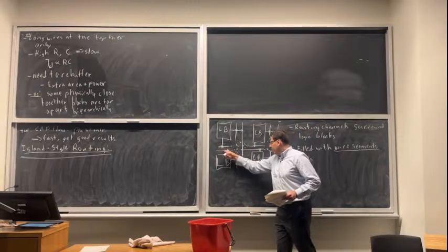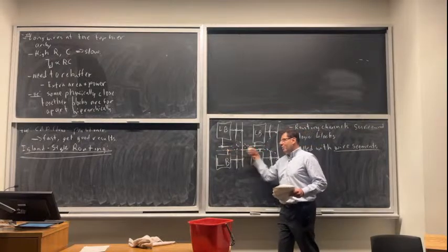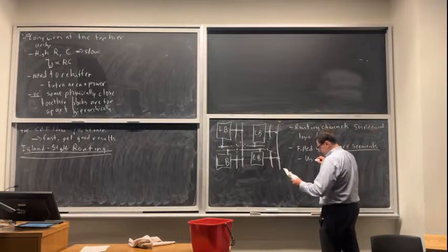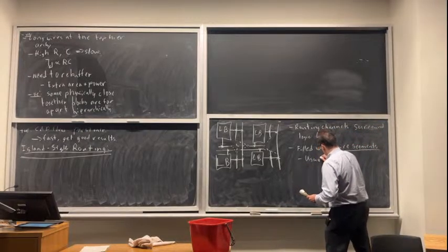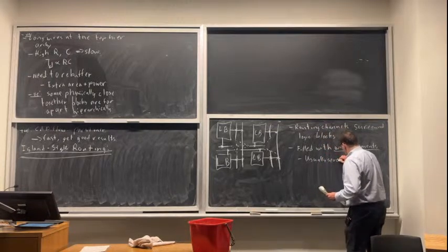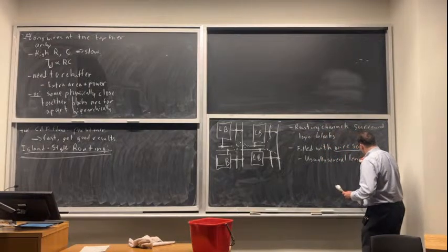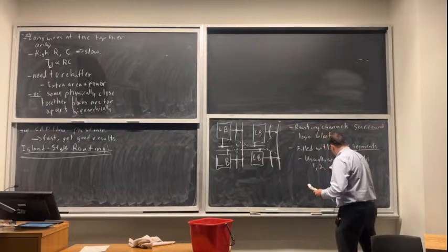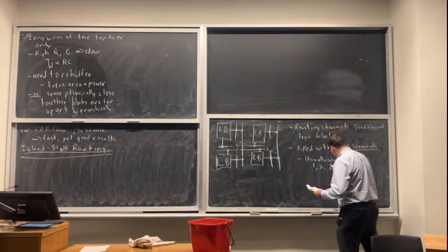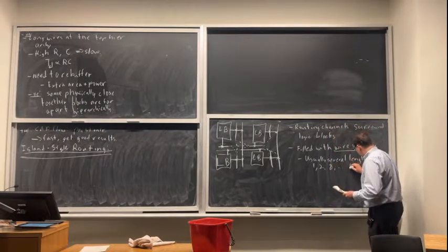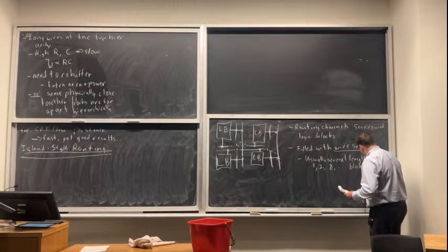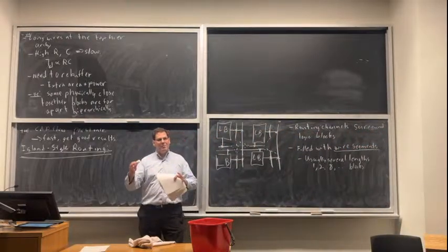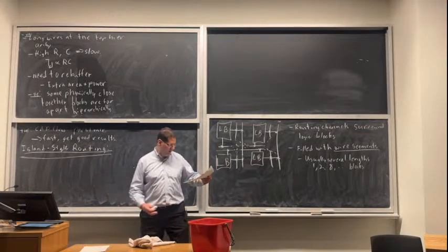This would be a length 2 wire. It goes past 2 blocks, and then you have to go through a programmable switch to keep going, and so on. So usually several lengths. We don't normally talk about their length in millimeters. We talk about it in terms of how many blocks they go past, like what's the topology.